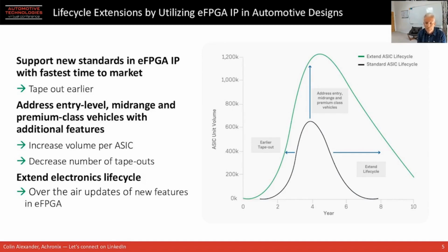Designers can accelerate availability of new platforms by taping out new architectures based on a new SoC earlier. They do this by partitioning the parts of the design that might change into an eFPGA tile. This allows the designers to incorporate support for the evolution of specifications, new algorithms, etc., without having to respin the ASIC. Additionally, the designer can simply reprogram the eFPGA to support the latest changes after the ASIC is in production or is in the field. So as you can see by this slide, there are significant benefits to be gained in using eFPGAs in SoC designs.